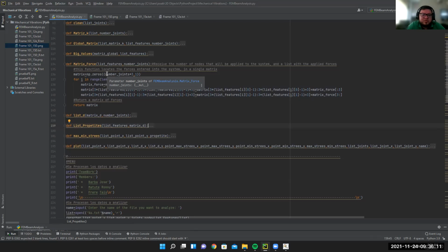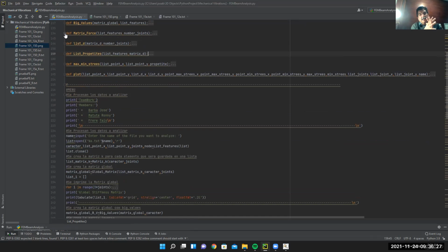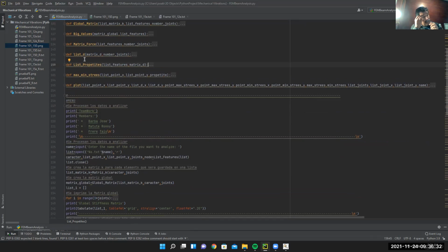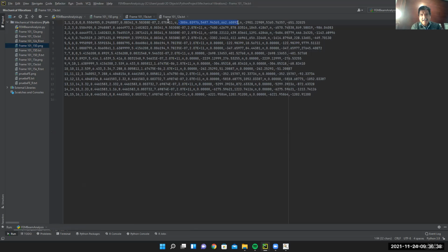The reaction is calculated by multiplying the displacement by the global matrix. No, no. Yeah, but it's still there. You have to differentiate those points where you have supports, where you have geometric restrictions. Okay. The boundary conditions, yeah. Exactly, the boundary conditions. Remember, the geometric boundary conditions do not allow the point to move or rotate, and in those points you have to calculate the reactions.